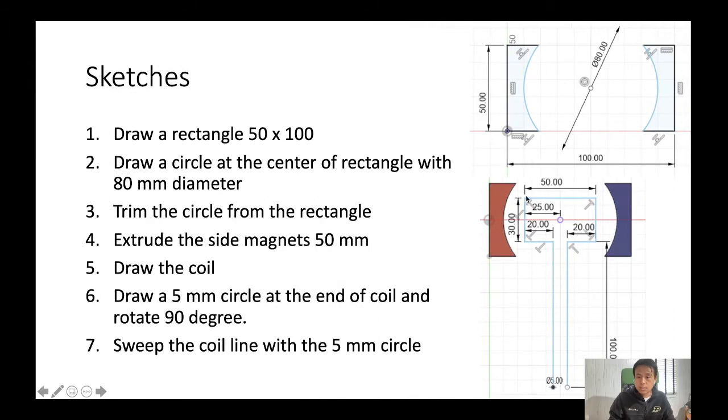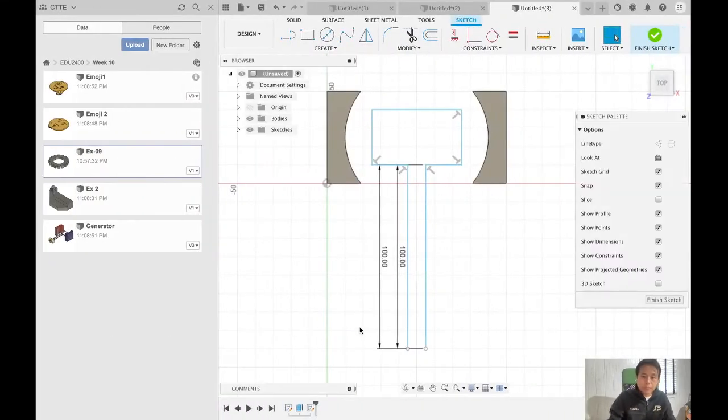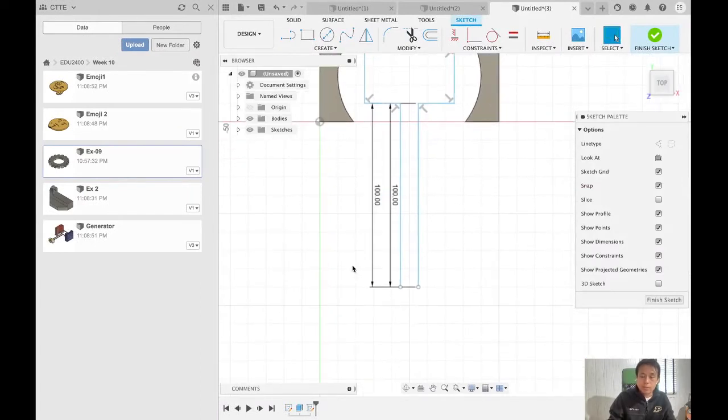This is the inside coil, and in the outcome, the coil has a round cylinder shape. So I'm going to make this shape by sweeping. You learned sweep, right? The sweeping feature in Fusion 360. To use the sweep, we need an original profile with this path.